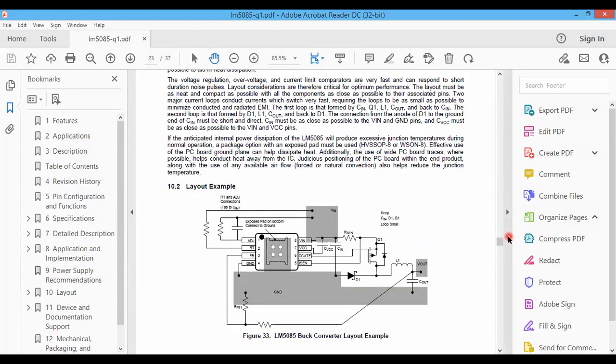So when you're designing the final PCB, these kinds of devices cannot be implemented on a breadboard, because if you implement them on a breadboard, there will be a lot of complications. EMI will be high and the ripple is high, and you can't get the desired result. You will still get the output voltage, but it is not the most efficient or the most effective method of doing that, right? So that's why you always have to build this switch mode power supply on PCBs.